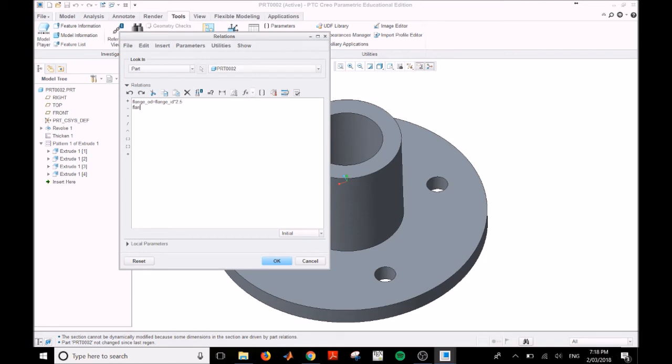So I'll set the flange PCD equal to the flange internal diameter times, let's go, 1.75. We've actually defined this PCD as a pitch circle radius, so I'll have to divide that by 2, my mistake.